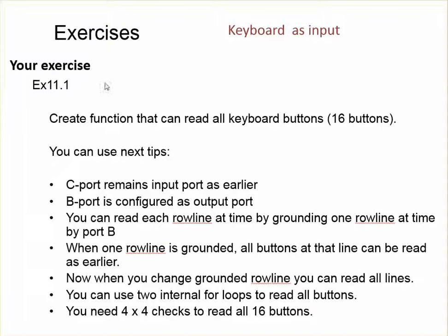So here's your exercise 11.1. The idea is to read all these 16 buttons. And now you are utilizing the information that you have tried earlier. So the keyboard reading could remain almost the same as you have already tried, and we just went through how to configure and how to use the keyboard to activate each row at a time.